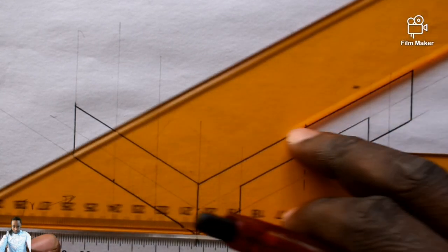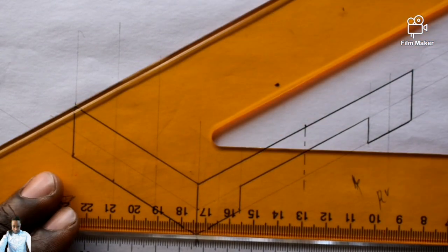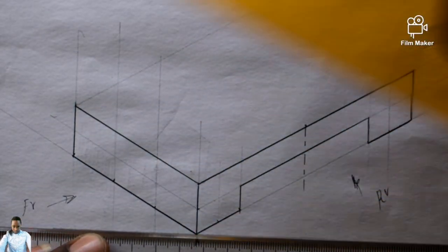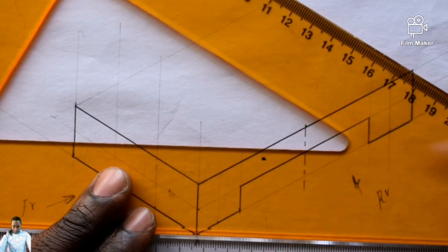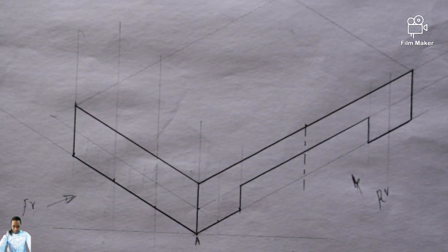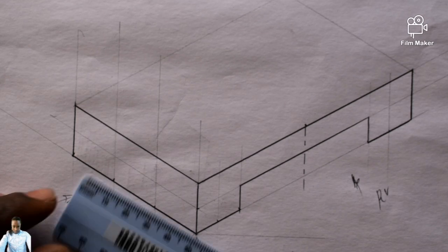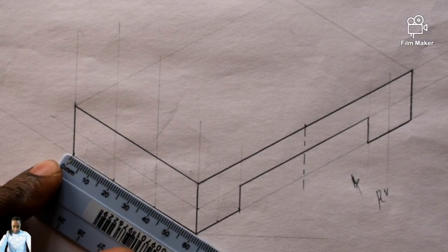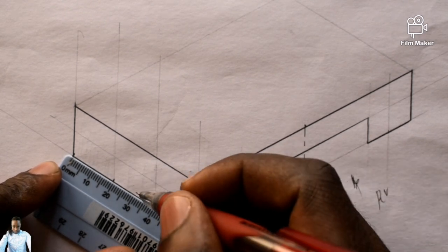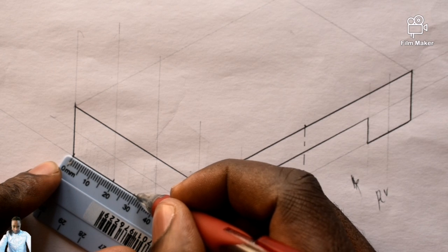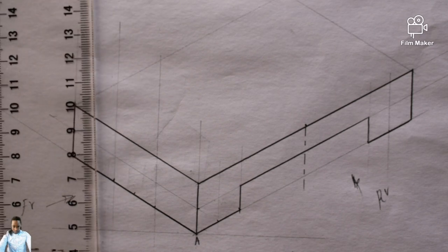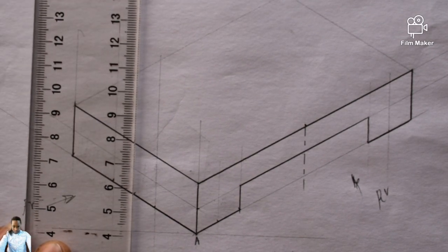So what is going to happen now? I'll pretend as if I am closing the top view, draw it faint like this. Even this other side, I'll draw it faint like this. Right, let me see what is the length of our front view. Is 60. Let's get to the half of 60, which is going to be 30. It's right there. There is our 30. So that one is giving us the center as well.